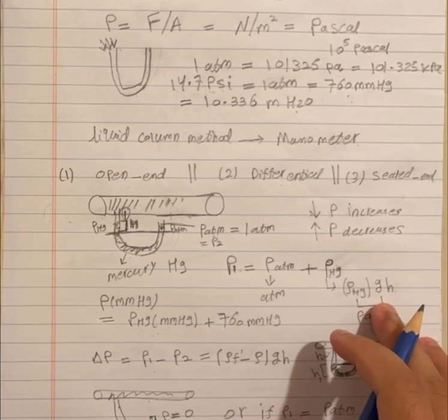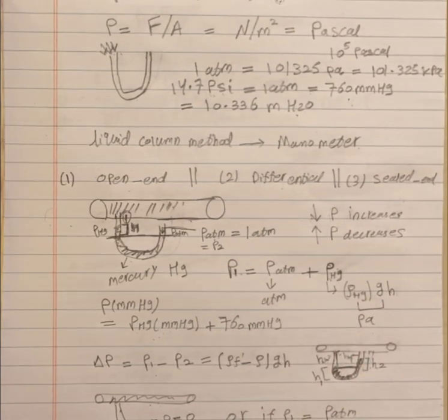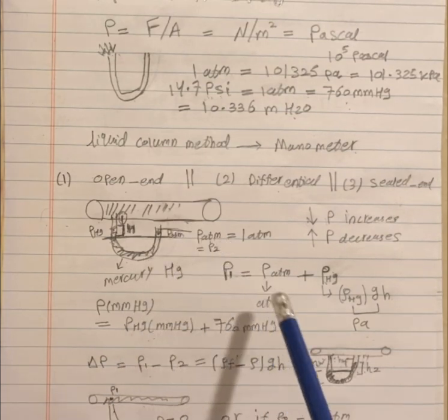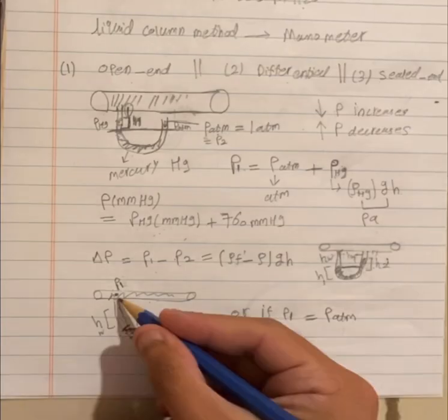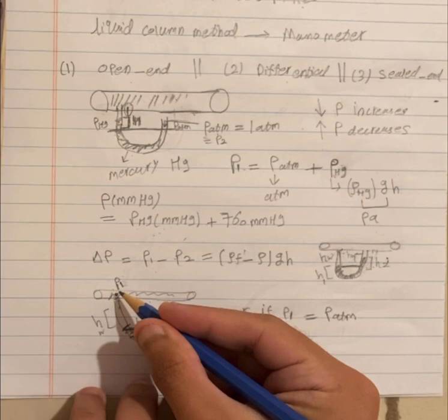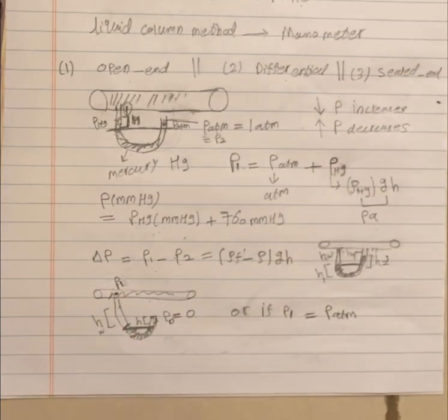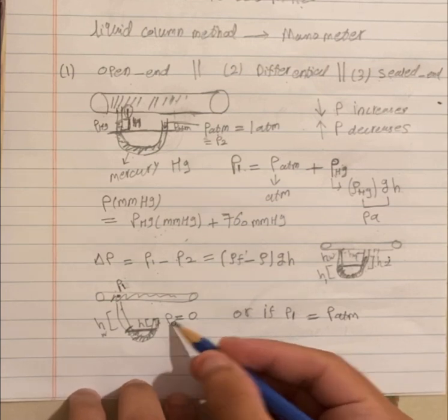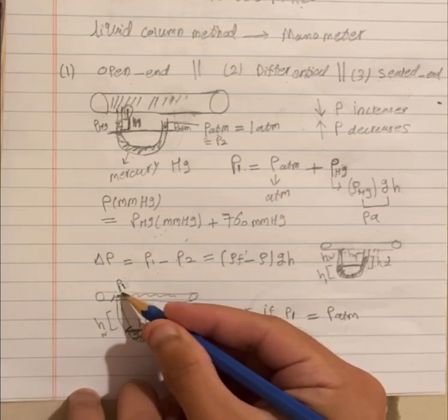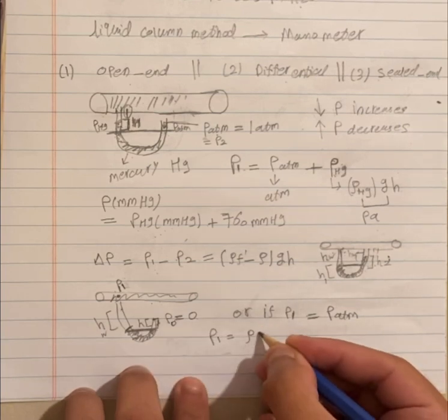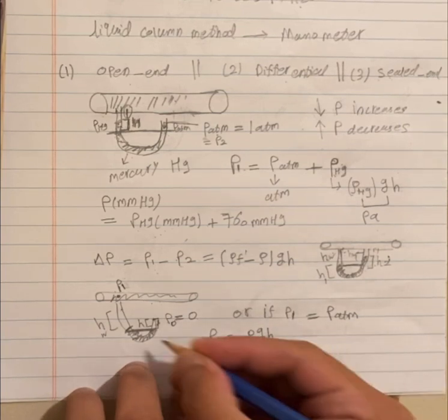So you will take a portion from every side, this one P1. And P1 will just be similar to this equation. It will be P1, the pressure we want to calculate, not in the barometer case, no, it's in the sealed end case, where P0 is equal to 0 and P1 is the pressure of the fluid. It will be rho of this white fluid, g, and then h of this height.